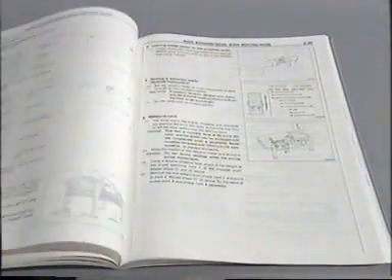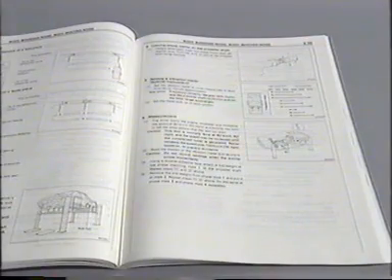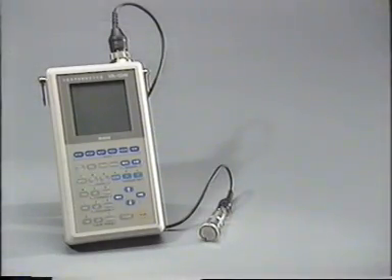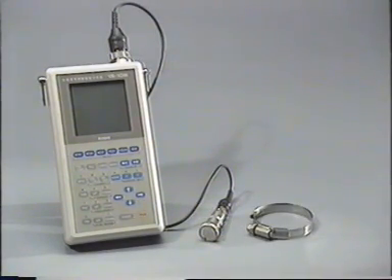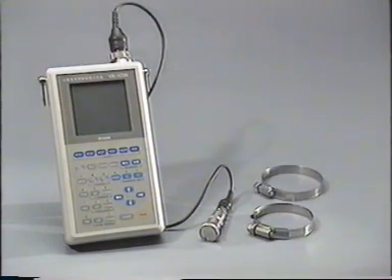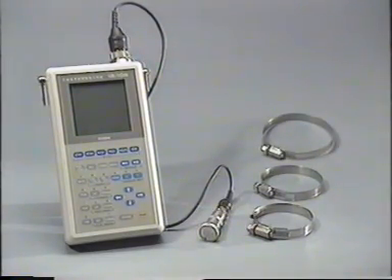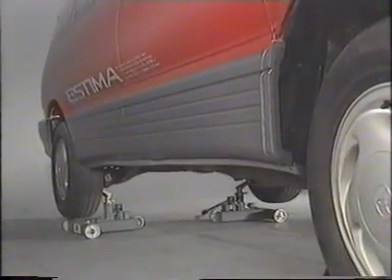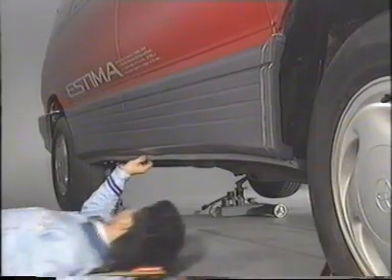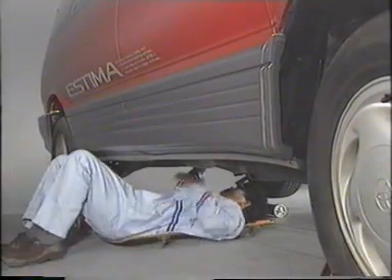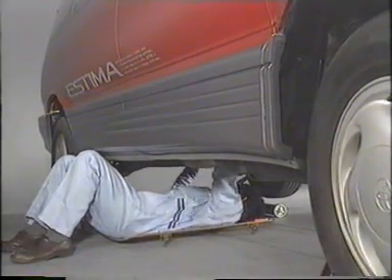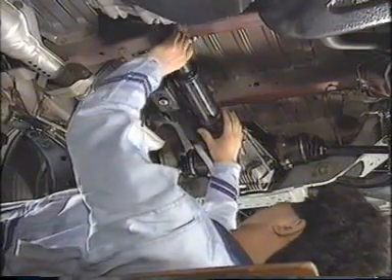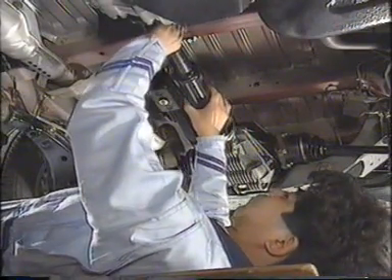Here we will only show the main techniques used in the propeller shaft balance inspection. Actually, there are 3 methods that can be used to check the balance on the car. First, we will check the balance using a vibration analyzer and some trial weights. Before you can begin the inspection, you need to jack up the vehicle, check the installation of the propeller shaft, and check the surface of the shaft for damage.